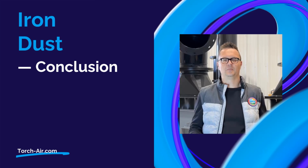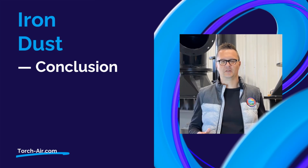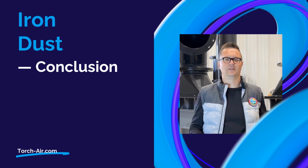Iron dust may look simple. After all, it is just iron, but fine particles of iron behave like a reactive, abrasive, and partially combustible metallic dust. They damage equipment, irritate lungs, and under NFPA 484 conditions, can ignite or contribute to large dust events. With strong airflow, high-efficiency filtration, abrasion-resistant design, and full OSHA and NFPA compliance, we can control iron dust safely and reliably.